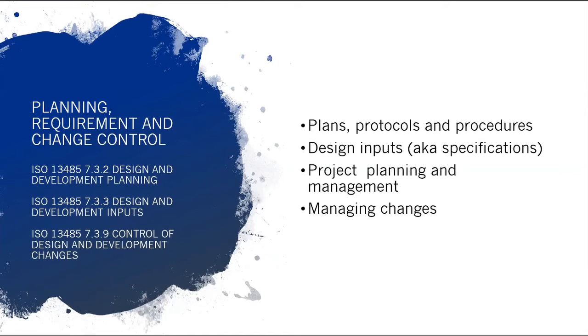Okay. To talk on the other points, design inputs, they're effectively technical specifications. If you're used to, as an engineer, having a technical specification, that's essentially what the design inputs are. So they take your user need that you need an LED indicator for power, and they look at 60601-1 that says a power indicator must be green, and it defines things. What brightness level does it need because of its ambient lighting environment, or it needs to be visible, etc. Those things are all design inputs that go into the technical design input specification.